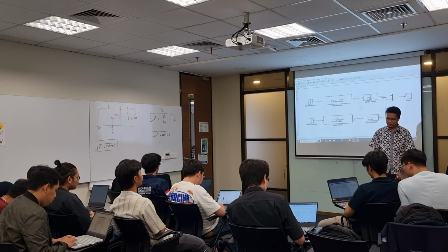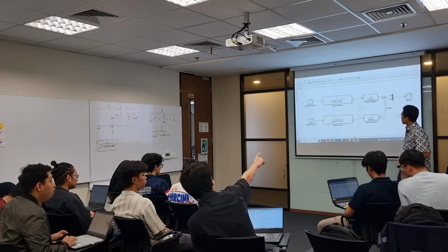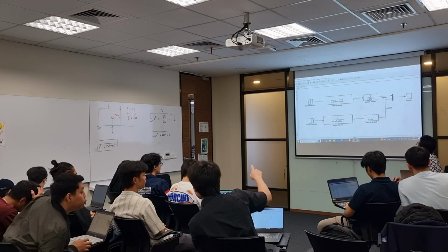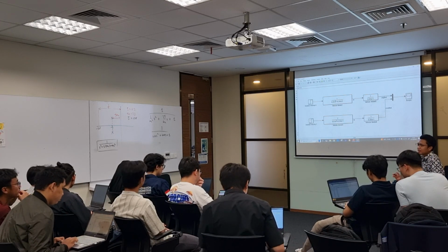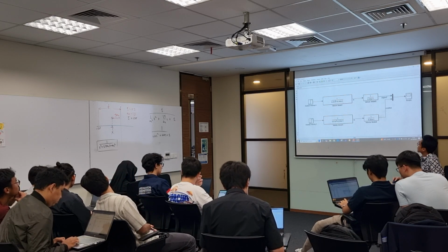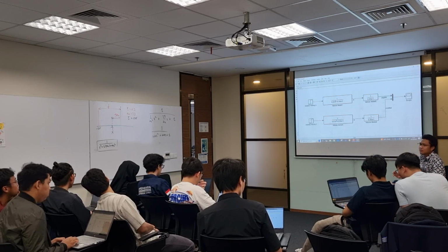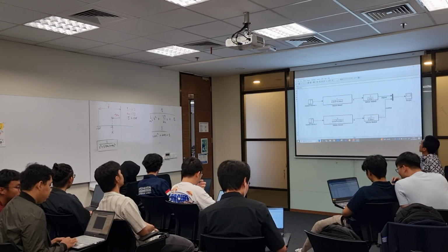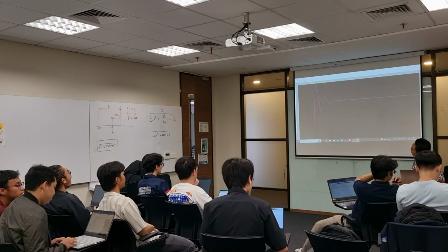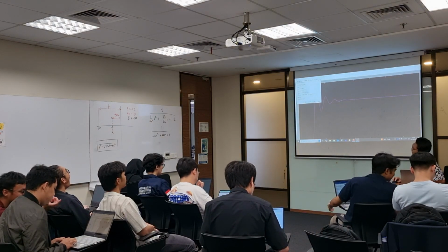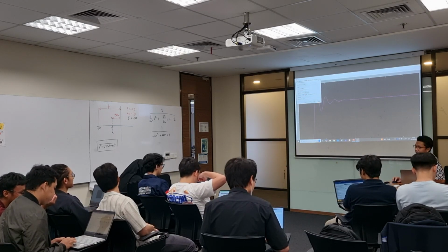This is the transfer function. So you see, now you label the signal. Can you do it? You double click on the arrow and then you write down the signal name. Then after that you double click on the scope, go into settings on the scope, and check legends. Check legends on the scope.